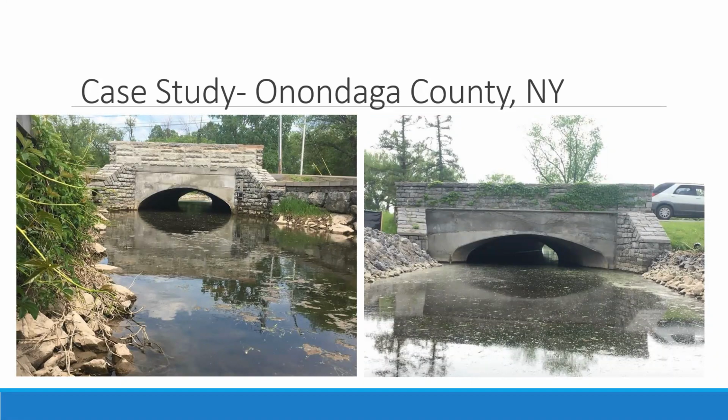So this culvert rehabilitation was successfully completed without traffic interruption and maintained the structure's aesthetic qualities. The newly rehabilitated culvert will provide long-term service to the citizens of Onondaga County. We can see here again, that's a great shot showing the design reducer inlet and how we navigated that bend, transitioning from a larger OD to a smaller ID in the culvert barrel.